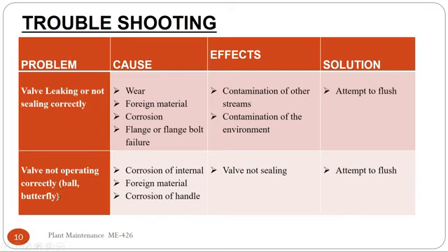Other problems are the valve not operating correctly, corrosion of internal parts, foreign material, and corrosion of the handle. The effect will be that the valve is not sealing properly. If the ball is corroded or eroded, then there is a chance that it will not operate correctly.